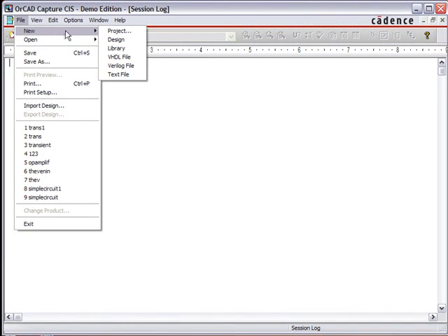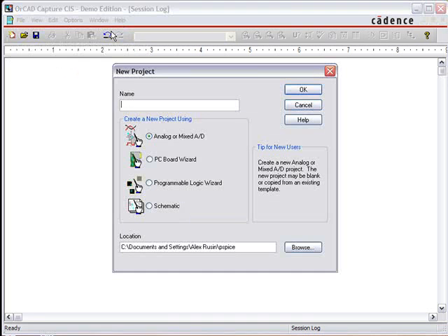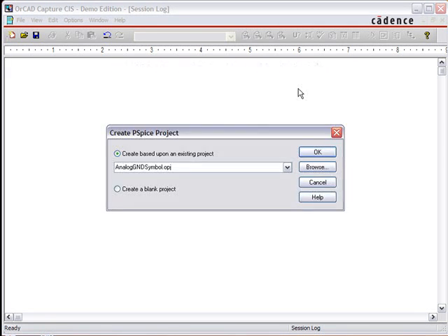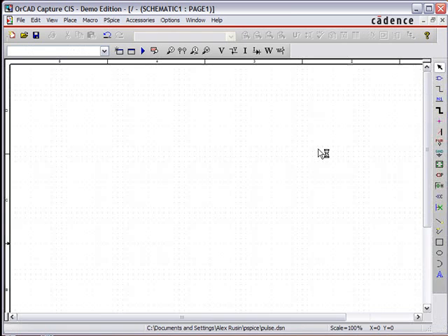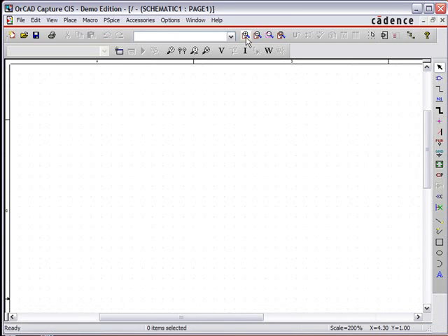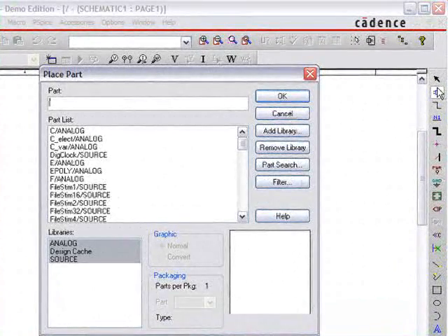In this part of the tutorial, now we will learn how to apply sinusoidal and pulse input signals. A variety of signals can be applied to our circuit. So far, we have dealt with a DC source only. From our menu, after we create our new file, we need to select vSine source. Okay, let's go ahead and select vSine.